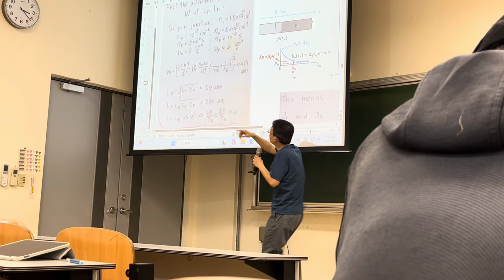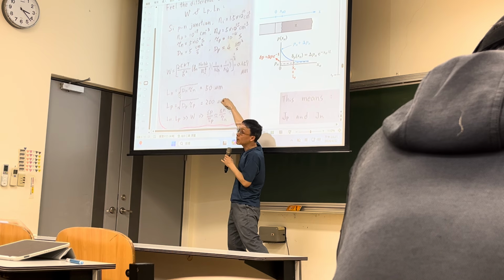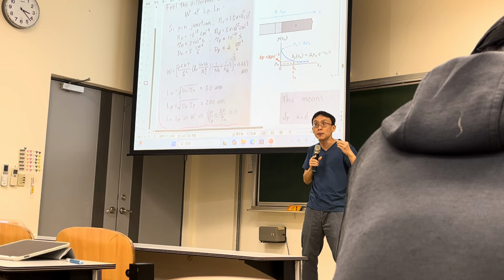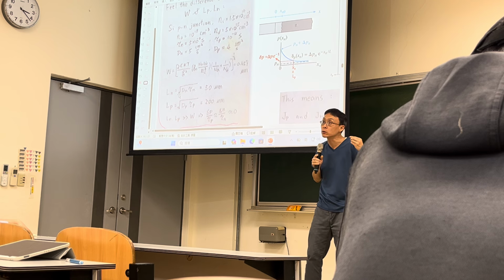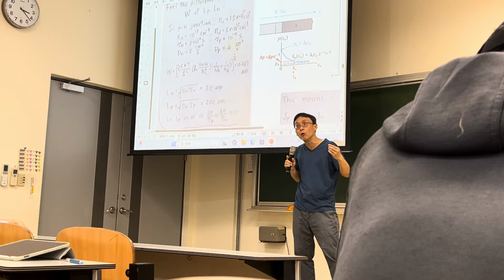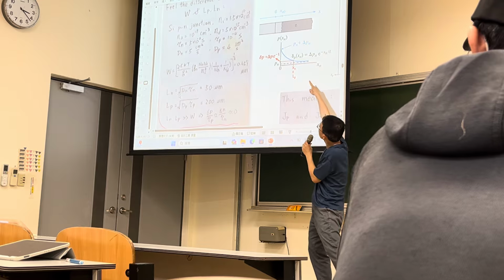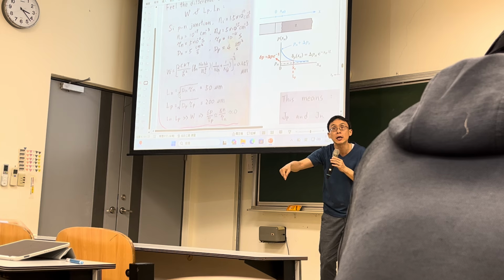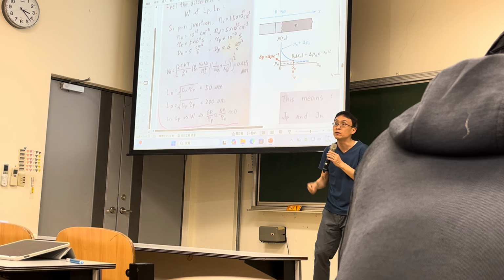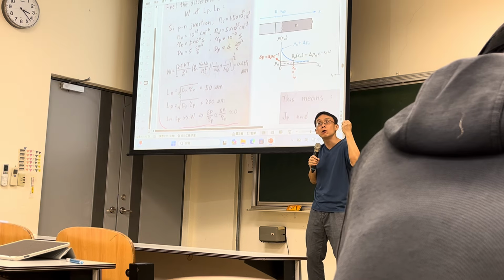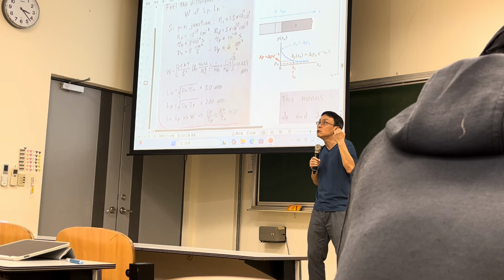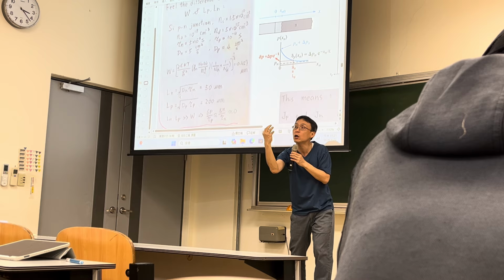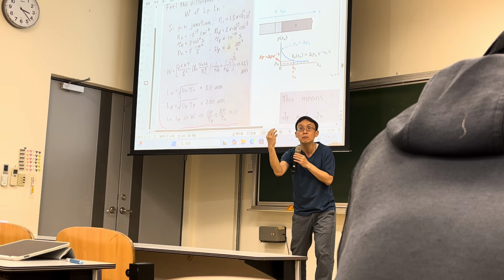So this 50 micron and 200 micron tell you how far the electrons and holes have to travel in order to make their concentration go down enough by recombination. If they only travel 0.5 micron, you can assume it's just around here, almost no change of the concentration, right?